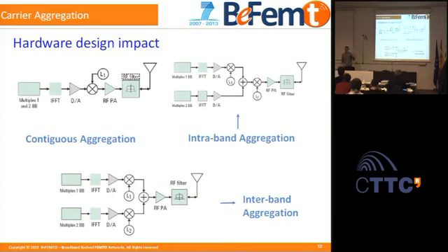Does state-of-the-art power amplifiers allow amplifying a signal on 800 MHz and 5 GHz at the same time? Several power amplifiers have been developed that work from 500 MHz up to 3 GHz without problem, with a different compression point, but fulfilling the LTE-Advanced requirements.